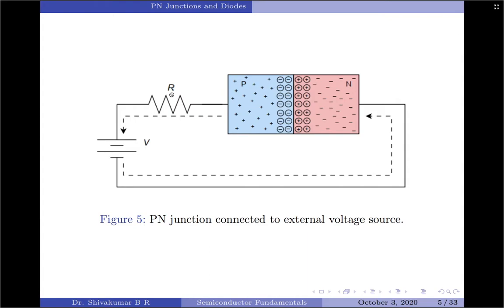If the voltage source polarity is reversed in the diagram shown here, the behavior of the PN junction is altered radically. In this case, the electrons in the N material will be drawn toward the positive terminal of the source, while the P material holes will be drawn toward the negative terminal, creating a small short-lived current. This has the effect of widening the depletion region, and once it reaches the supplied potential, the flow of current ceases. In essence, we have increased the size of the energy hill.